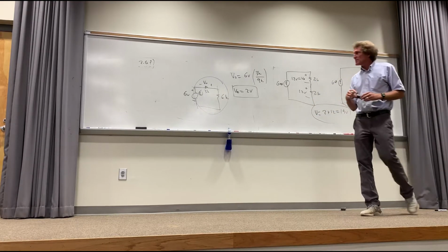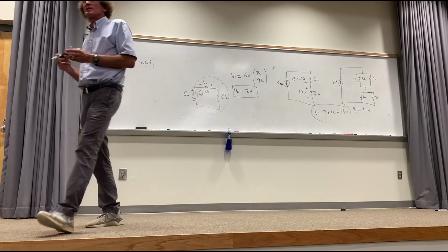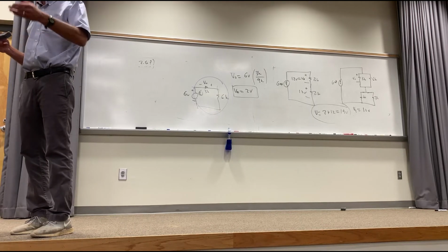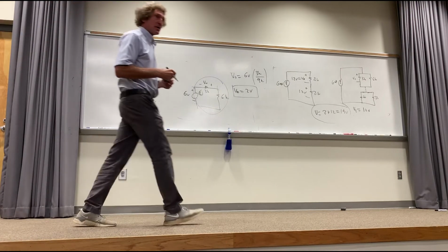If you want to try something, go to the original circuit and do the problem using nodal analysis. Make sure you get the same result. You will. Then with mesh, make sure you get the same result. And that way you confirm its validity.